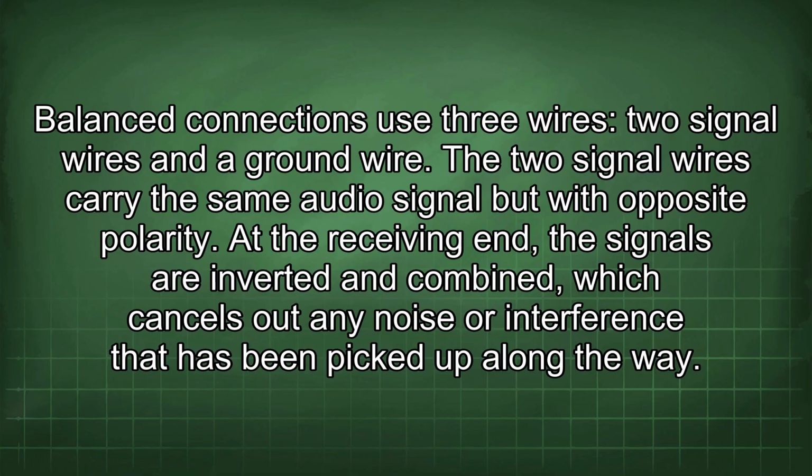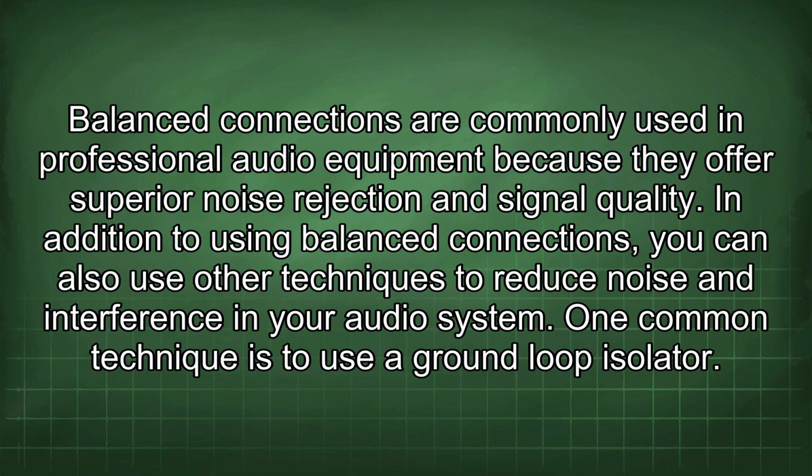At the receiving end, the signals are inverted and combined, which cancels out any noise or interference that has been picked up along the way. Balanced connections are commonly used in professional audio equipment because they offer superior noise rejection and signal quality.